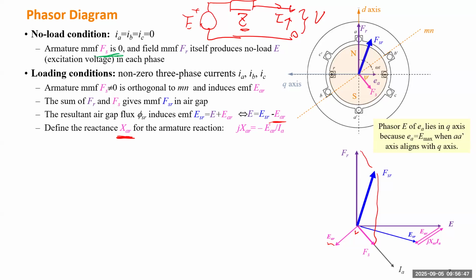So inside the generator there's some reactance, and this Z will be contributed by that reactance. That reactance carrying the current will create a voltage drop. That explains why the terminal voltage of the generator can be smaller than the internal voltage. Further, you can also add the resistance and some leakage reactance. For a perfectly designed generator that can be ignored, but when there's an air gap, some flux linkage does not contribute to those voltages and will be lost. So you can also add that part.